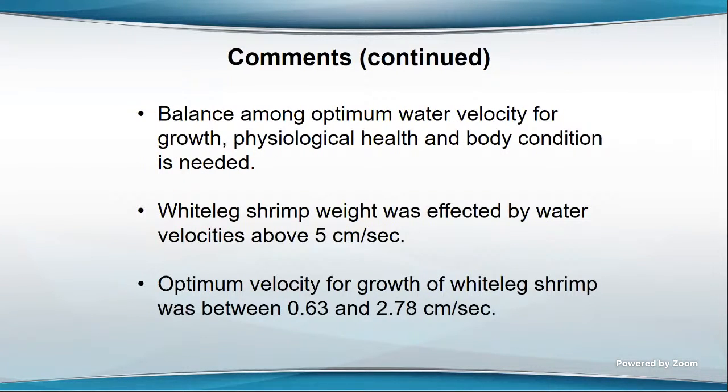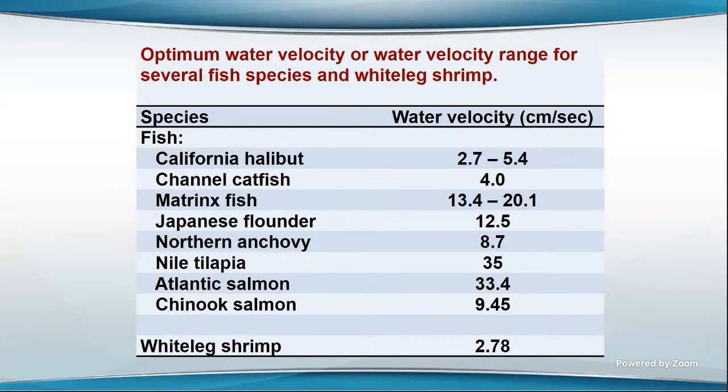And in all this aerator design, all I was ever involved in, we weren't really concerned so much with the water velocity. We were trying to get the maximum oxygen transfer. So we really need to work out the best water velocity. That's just some optimal water velocities for several different species. Some can have a much higher optimum water velocity than others, but this has never really been considered much in aeration.